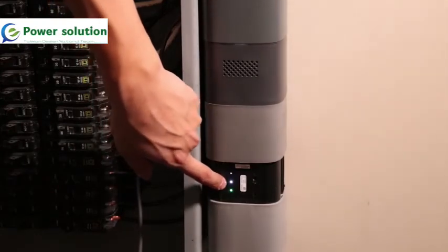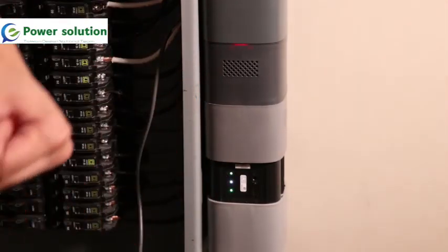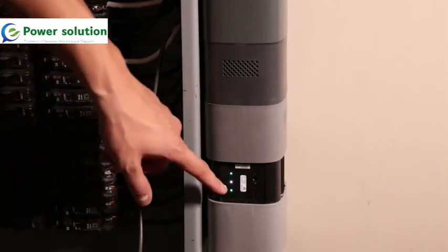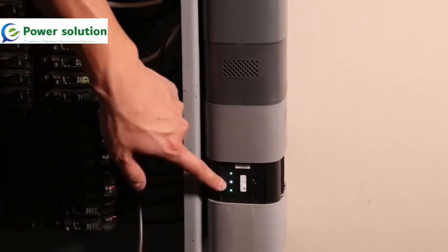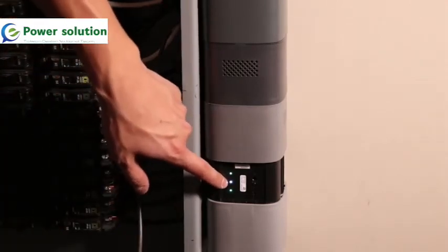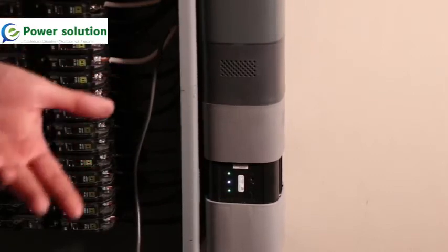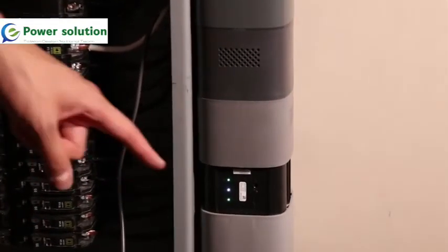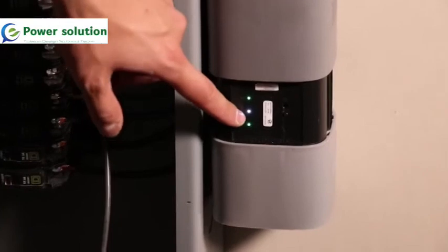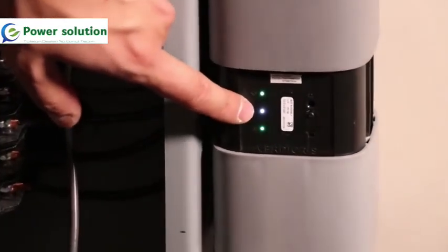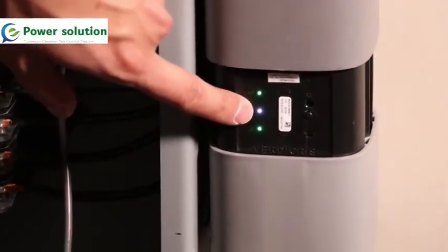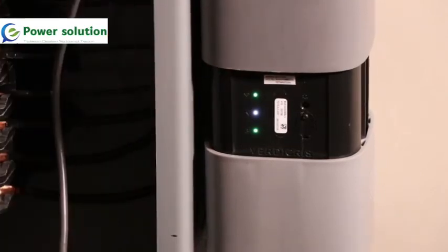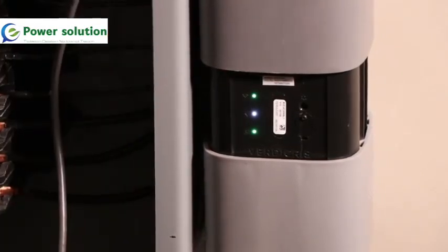For the voltage check, if the voltage detected is not reading the right phases or reading the right levels, there's a chance that you've maybe connected the phases of the voltage incorrectly, and that would be something to check if this light turns red. That means it's not a compatible voltage configuration that the system is detecting.